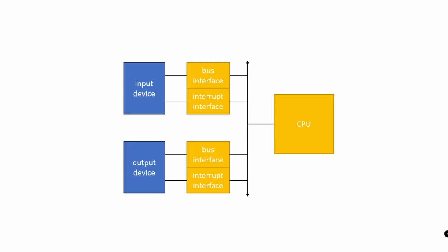The sensor's bus interface provides an addressable interface for the Hall effect sensor. The interface checks the address on the bus and compares it to the assigned address of the device. If they match, the interface responds. The interface must also check whether the requested operation is a read or write.